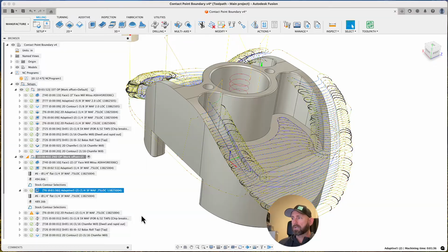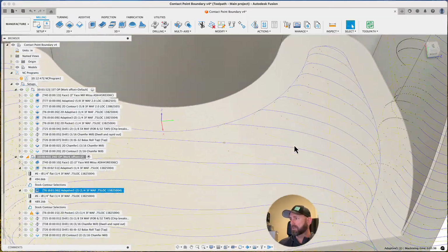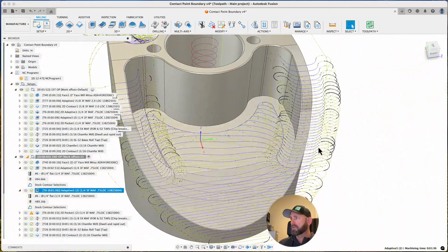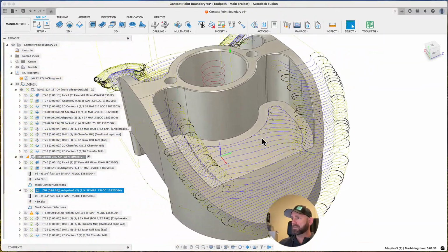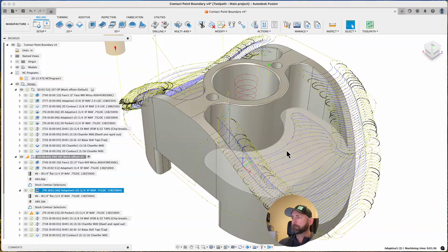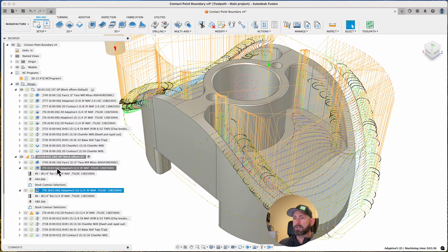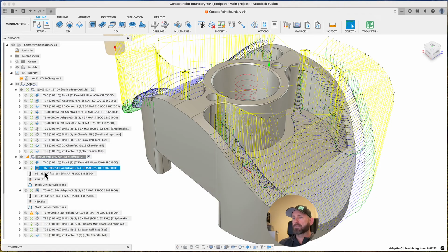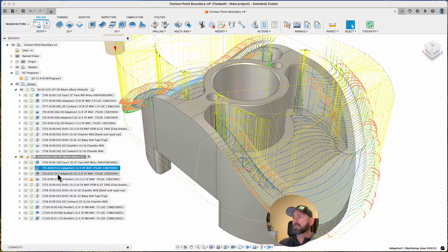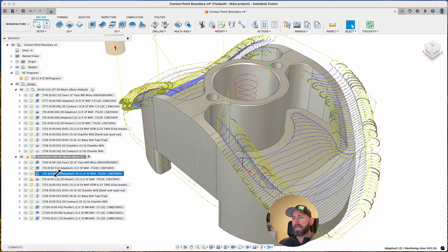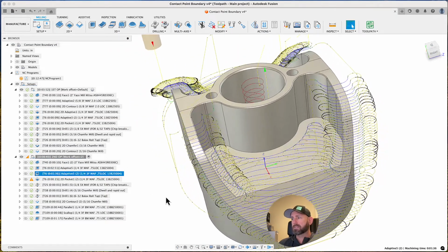And then when we click on it, we can see down in the toolpath, you actually have way fewer points. You actually get some more points up here, but that's because of some settings that we'll talk about in a few minutes. But the cutting motion on my Haas machine is going to be way better than the cutting motion of this. And that's before you get into the G187 smoothing settings. And then the toolpath is basically the same file size.